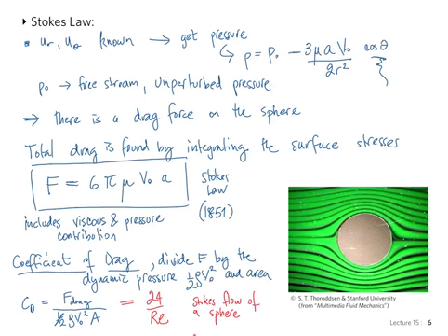And this is very useful in many applications, like I was explaining, settling, and many environmental problems use settling speed. We can calculate the terminal speed based on this by doing a force balance between the weight of the particle and the force of drag, and you can get a terminal speed. It's called the settling speed. This is very useful in many applications, both industrially and environmental fluid mechanics.